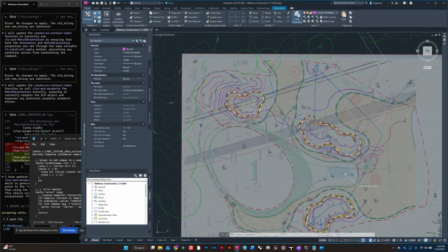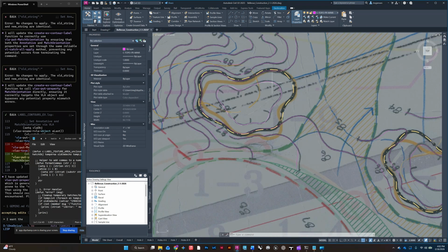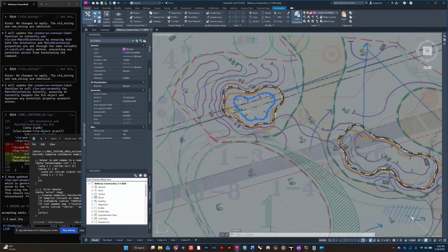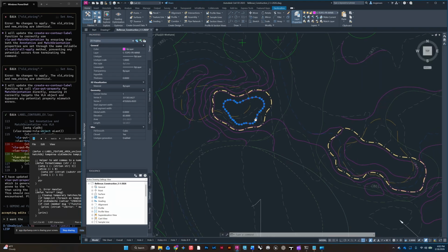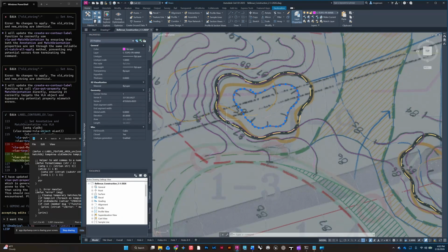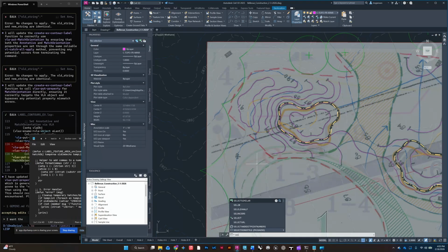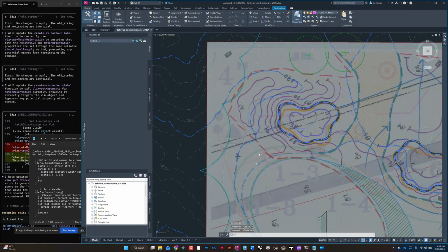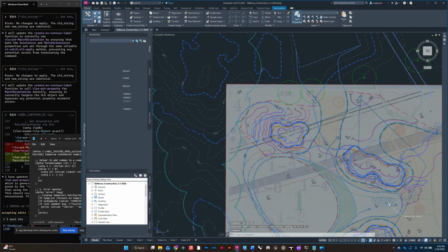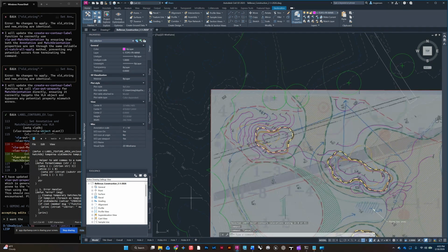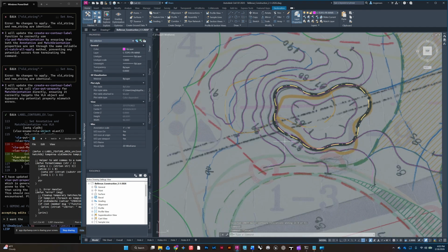So the next thing to do is these low points, these low lines. So this is the bottom of bunker 85. Well, I guess the first thing to do would be to select all of these that are major lines. I actually think I might have a Lisp created that selects majors, but it selects majors on everything. So a Lisp could do this for you.